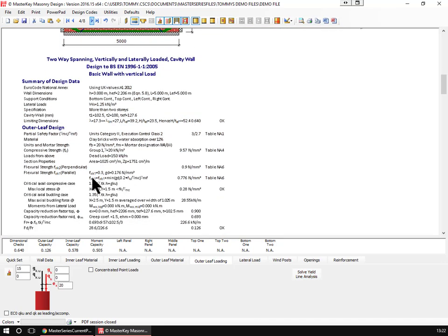Naturally, you will also understand that we get improved flexural strength due to the self-weight or concentric load weights on the wall, so we actually end up with an improved flexural strength due to the axial load, as long as it's not causing a problem with the axial itself.